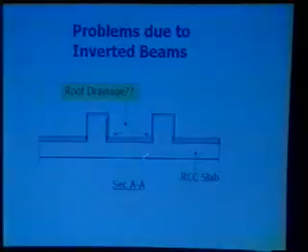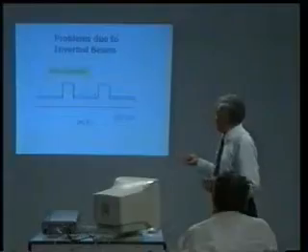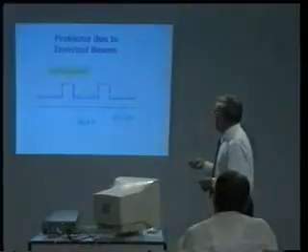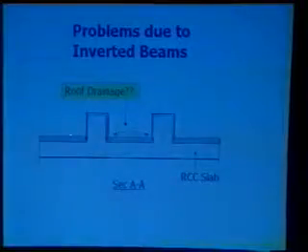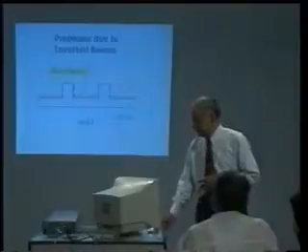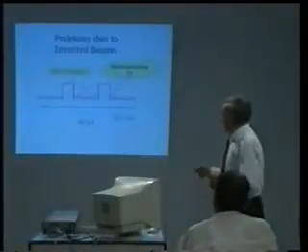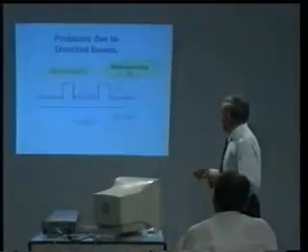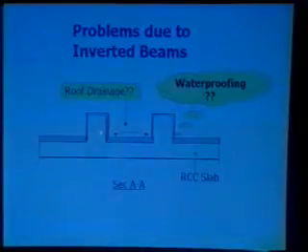It can only be transmitted in the longitudinal direction. Sometimes what people do is provide pipes to drain the water through this, which is not an effective way. It can get blocked with even the smallest leaf or paper that flies onto the roof. Now, you can provide the waterproofing over here, fine, but what do you do about the waterproofing on top of this?